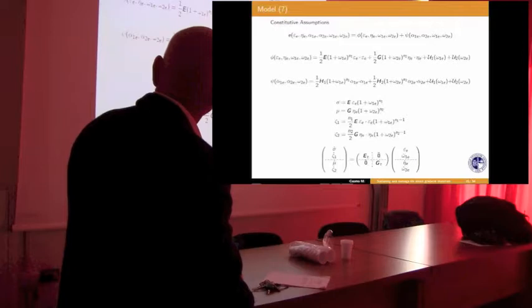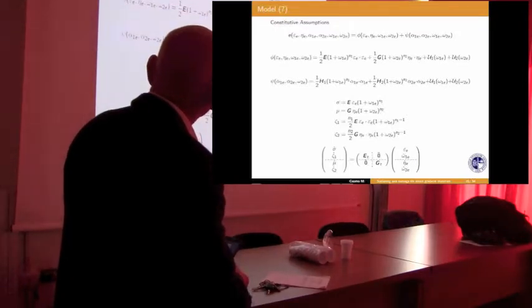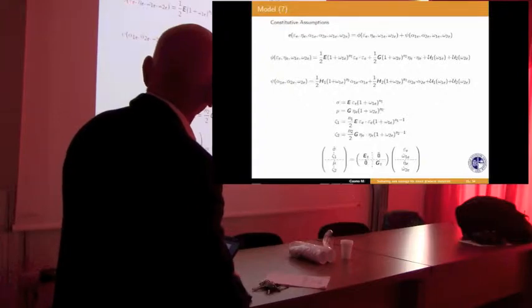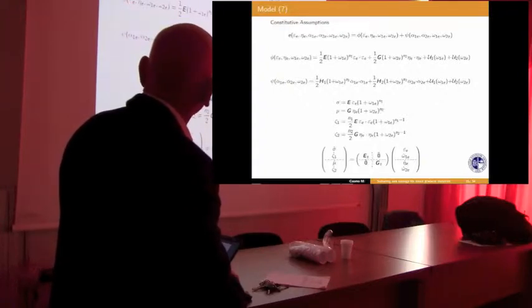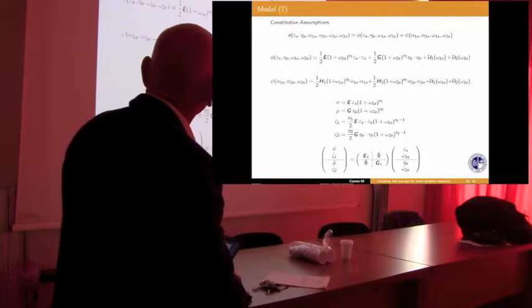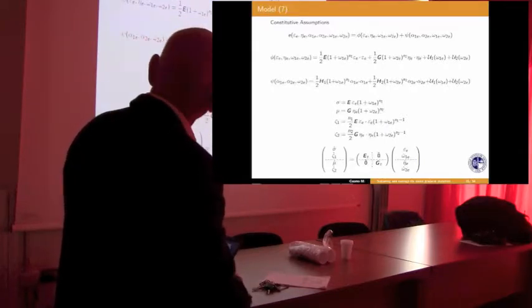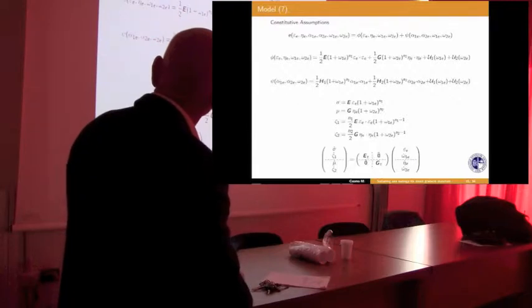The assumption is that the internal energy is split in the sum of a strain energy, a function of the deformation, gradient of strain, and damage, both damage variables. This is a hardening internal energy, a function of the hardening variables, local and non-local, and both damage variables. There is one missing here, okay.